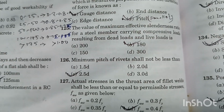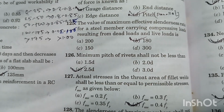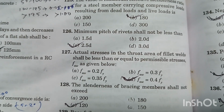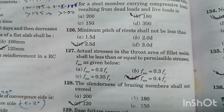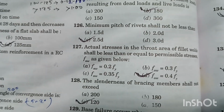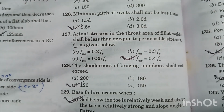Question number 126. Minimum pitch of rivet shall not be less than 2.5 d. Option C is the right answer, where d is the nominal diameter of the rivet. Question number 127. Actual stresses in the throat area of fillet weld shall be less than or equal to permissible stresses FAW as given below. Option D is the right answer, FAW equal to 0.4 into Fy. Question number 128. The slenderness of bracing member shall not exceed 120. Option C is the right answer.